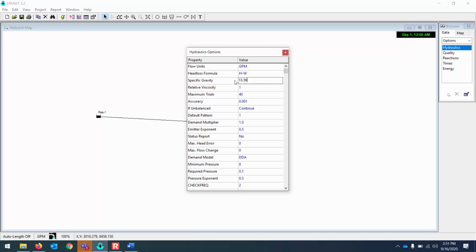times that of water. Or if we had oil, for example, we know oil is lighter than water. That's why it floats on top of water. So if we had some oil like SAE 30, maybe we could go to the back of the book. For instance, I think your textbook in table A5 mentions the specific gravity of water at different temperatures. So you could look up the specific gravity at 120 Fahrenheit relative to the specific gravity at 40 Fahrenheit and find some multiplier to add in here for the specific gravity. That's going to change what the system knows is the density of the fluid.